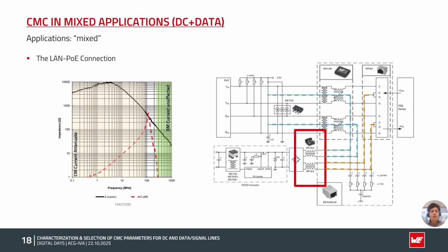In a mixed application, we implemented our SL5 series, selected for its high rated current value and its ability to provide both common mode and differential mode attenuation at the desired frequencies.